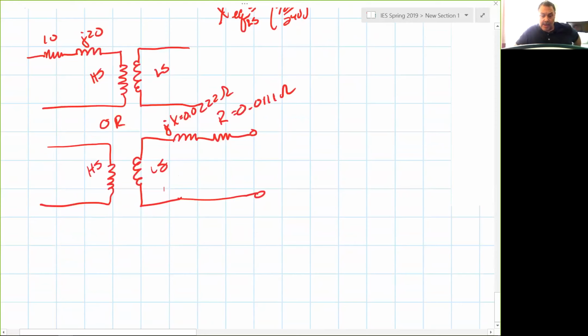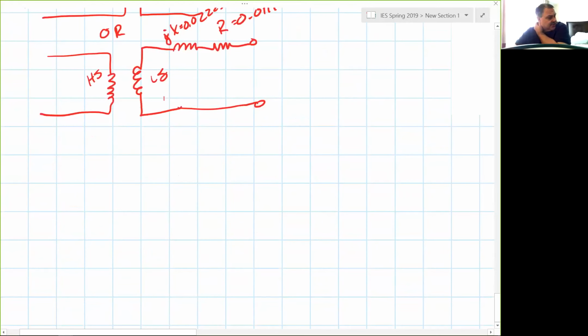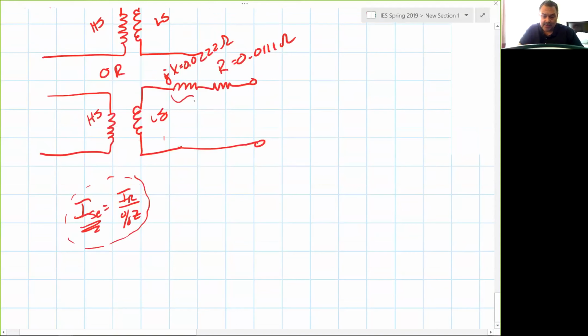Okay. Now, where we're headed, I don't know if you guys remember this from machinery and controls. We'll talk about it a little bit in National Electric Code, but remember, I short circuit equals I rated over the percent Z. That gives us the fault current on the secondary of a single transformer. What I'm revealing to you is where this all comes from.